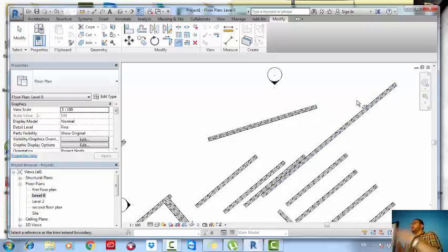In AutoCAD, the two lines should be intersecting after the extend, right? If they don't intersect, it will not be extended. Here no, it will extend your objects towards the extension of the other ones.